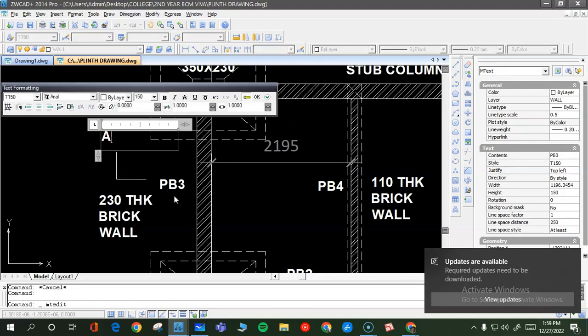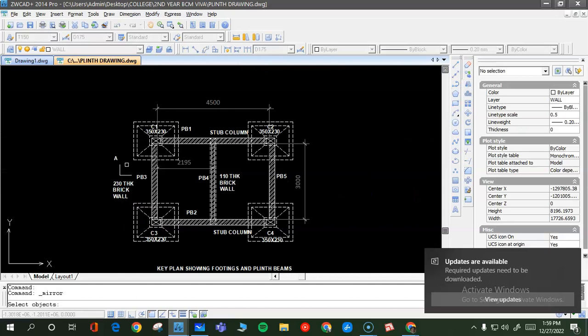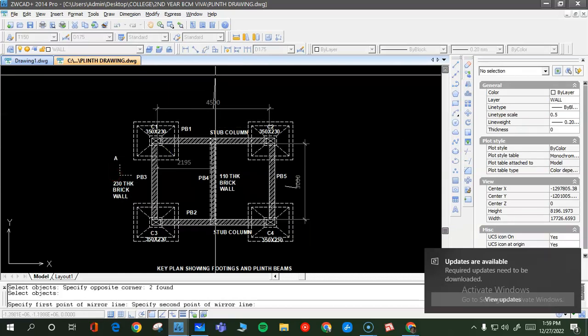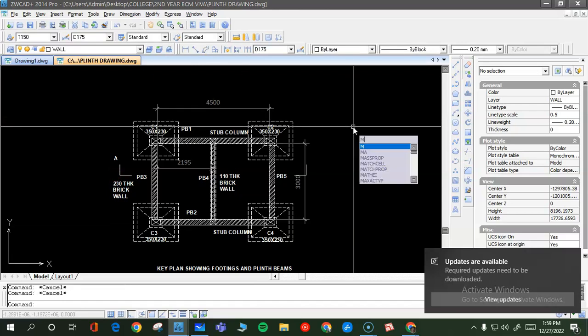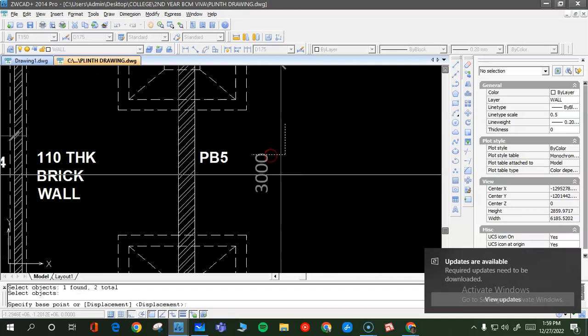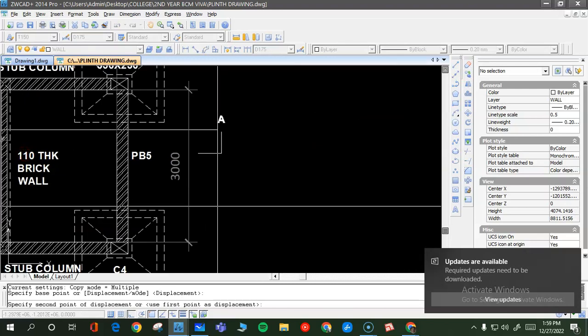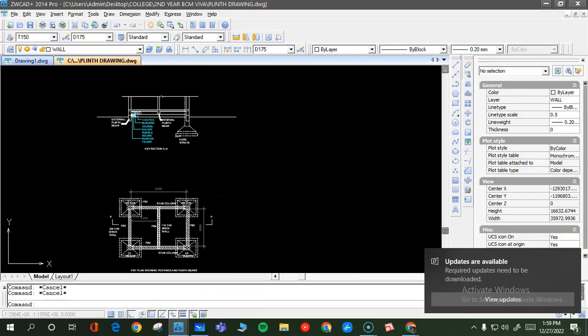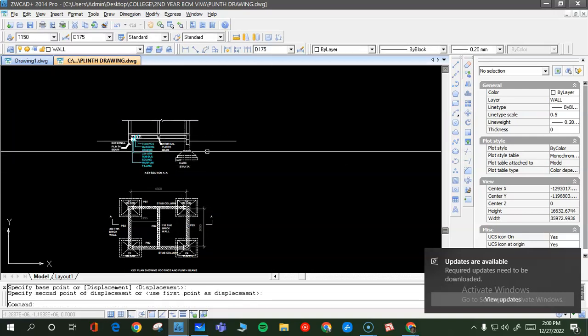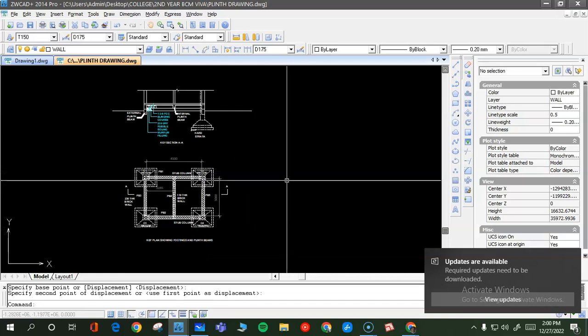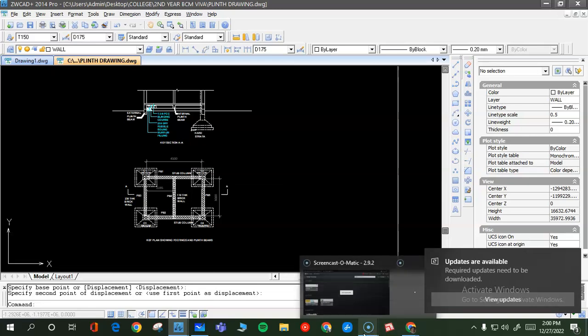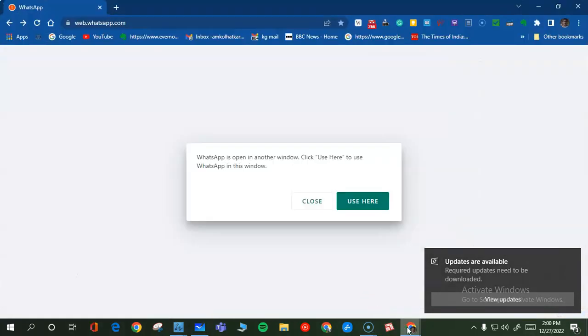So this will be AA, and the same thing you will draw here. So don't forget to show the section line and mention it here when you are drawing the key section AA. Compose the sheet a little bit properly so that it comes neatly. Before actually starting the drafting, just try to find out how much space you are going to require for drawing it at 1:50 scale. So this is part 1 of the question which we have solved, the first part which was at a scale of 1:50. Let us go back to the question here.